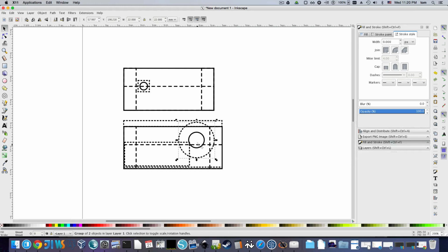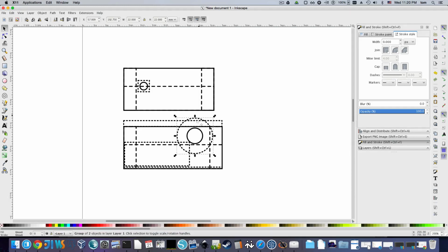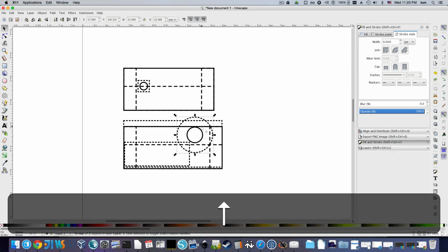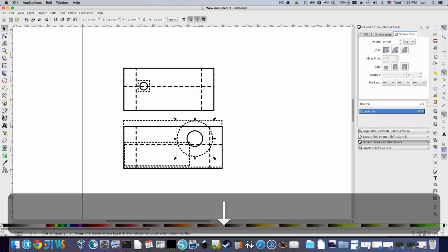We also have to account for the wire coming out of the back of the 510 connector. If we put it down here in this very short box, it's going to run into the batteries and the connector and everything. So ideally we don't want this hanging over the edge of the lid, and we don't want it too close to the edge of the box right here or it'll break, and we don't want it running into the batteries.